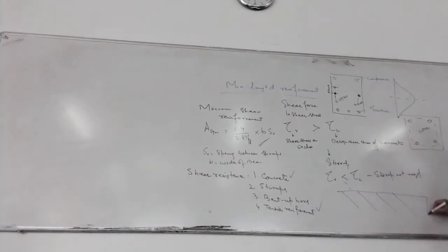This is the beam reinforcement. You can also provide the inclined stirrups. Where bent up bars are provided, their contribution towards shear reinforcement shall not be more than half of that of the total shear reinforcement. ये bent up bar की जब बात आएगी तो वहाँ पर हम करेंगे. So right now we are concerned about stirrup. Shear reinforcement shall be provided to carry a shear equal to Vu minus tau c b d.